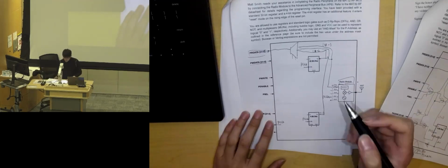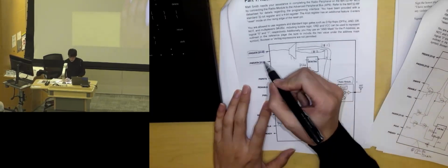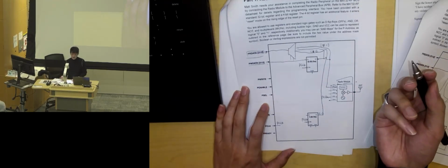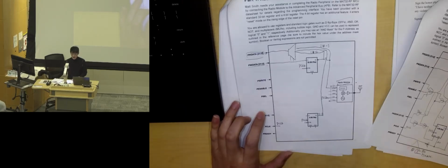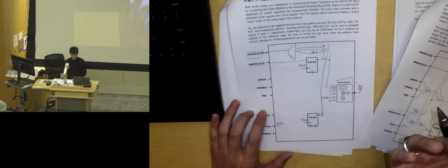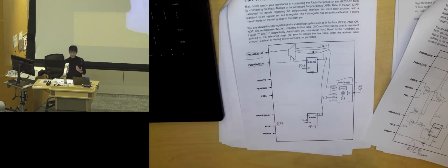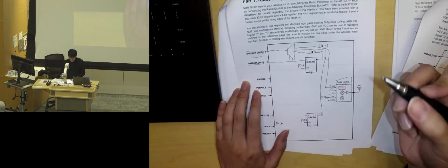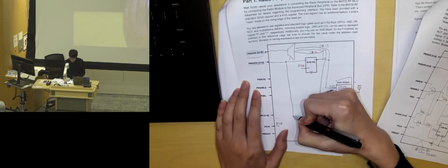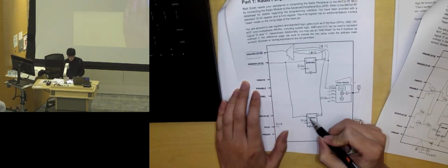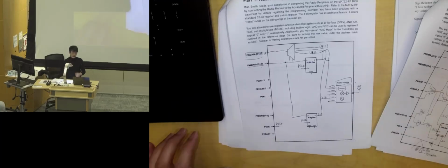So basically, that kind of gave away where this P-write data is going to go. Chances are it's going to go to the 32-bit register, because that's where you write into, and then that gets passed down to the data in the radio module. And what's the other place this needs to be? This is the only path where data can be written into these peripherals, right? So chances are this is going to be connected to this one as well. But this is 32-bit, and this is only 4-bit. What do we do about it? You will check the register in the data sheet, and it will tell